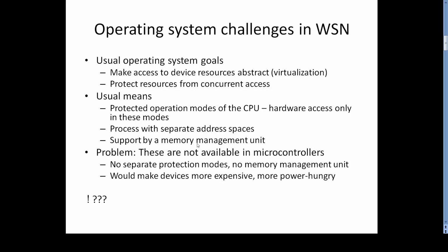But there is a problem with the microcontrollers. These separate address spaces and memory management unit, these usual means are not available in microcontrollers. So we do not have separate protection modes. We do not have a memory management unit. And this would make devices more expensive, and in turn, they also will consume more power.